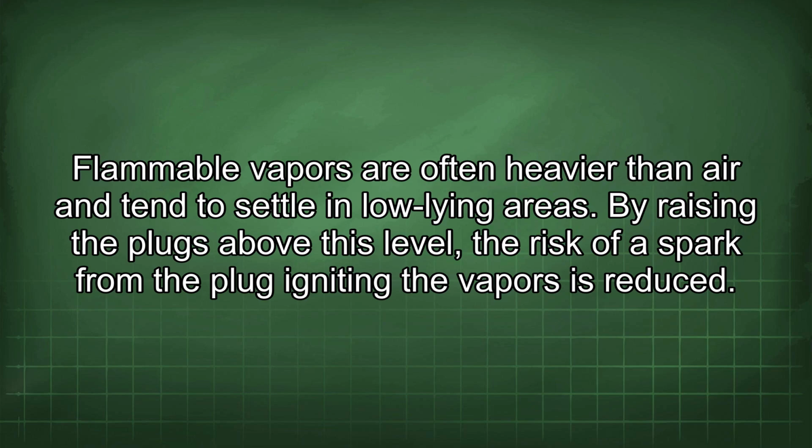Flammable vapors are often heavier than air and tend to settle in low-lying areas. By raising the plugs above this level, the risk of a spark from the plug igniting the vapors is reduced.